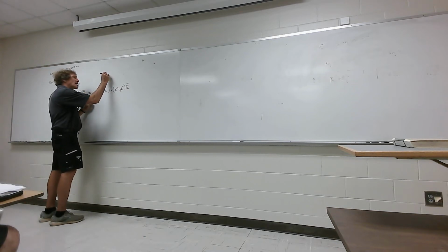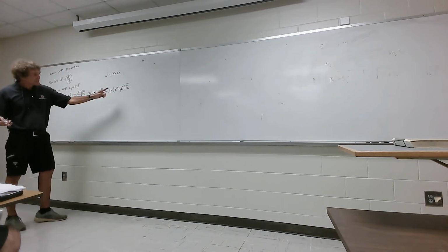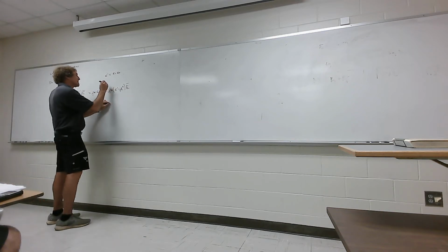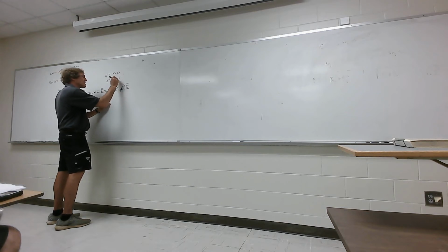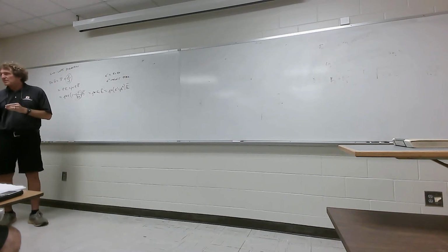Now epsilon prime is just epsilon relative times epsilon naught. It's what we're used to. This term right here dictates dielectric losses, bound charge that's just frictionally heating. So the epsilon double prime, that's the loss term. And it is a strong function of frequency.